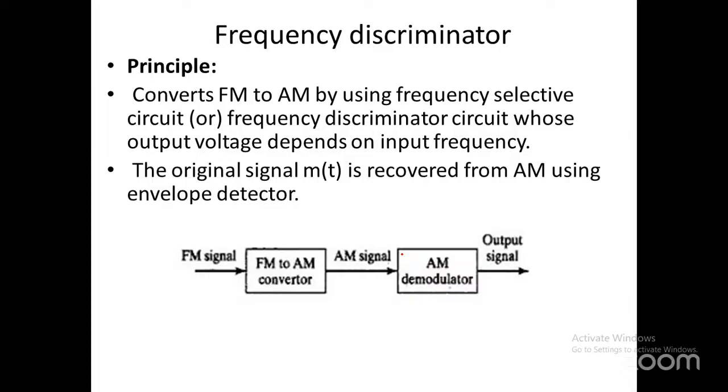The output voltage of the VCO is made to vary according to the frequency of the signal. Because the FM signal has a number of harmonics, all harmonics carry the same message. Selecting one of the harmonics and applying our VCO there is called a phase locked loop. The output voltage keeps changing based on that frequency. So each and every frequency component will have different voltages, which is almost the same as an amplitude modulated signal. Then use amplitude demodulation units such as an envelope detector or rectifier detector to detect the output.